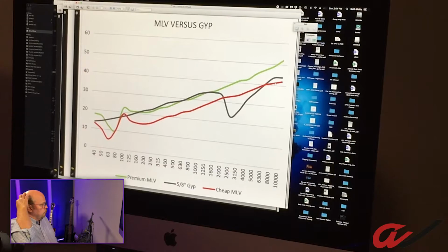Now the question of whether or not one is really identical to the other, hard to say. But basically you've got different types of mass-loaded vinyl. Now the theory is that you take MLV and you stick it in a wall, it fixes all of this. And it might, but that depends on how it's installed, because one of the things nobody ever wants to talk about is when things are in contact with each other.